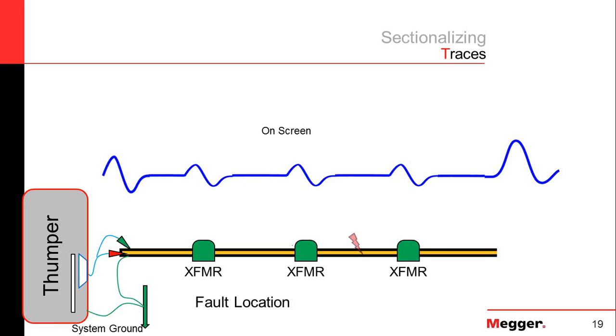Now, sometime in the middle of the night, one of these cables failed. It faulted, and everybody on this loop lost lights, lost power. So a troubleman comes out there, and his job is to figure out where this fault is so he can isolate it and restore power by looping around, feeding power from either direction around an isolated faulted cable.